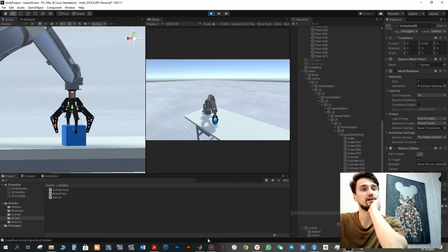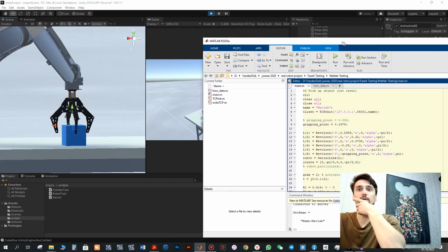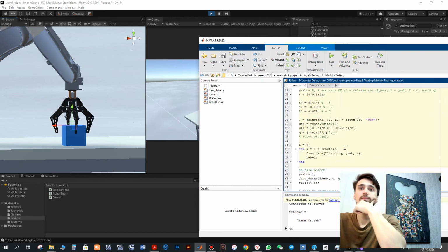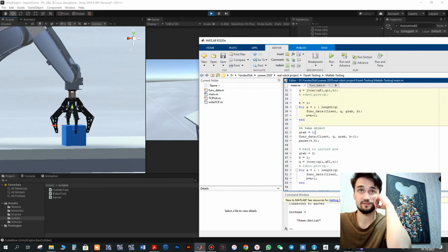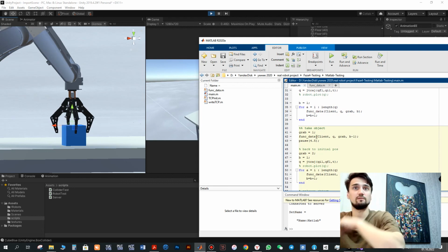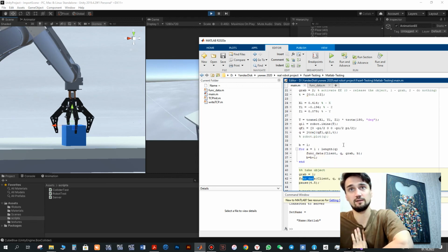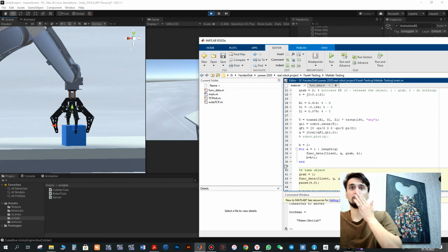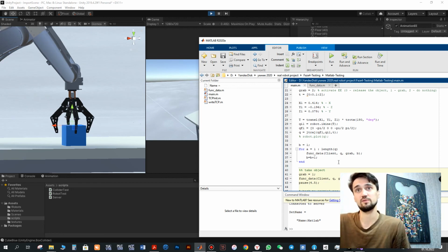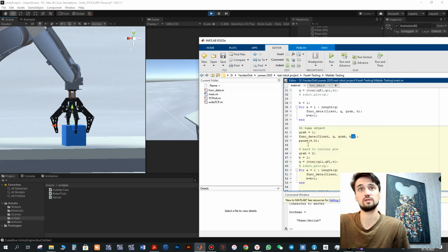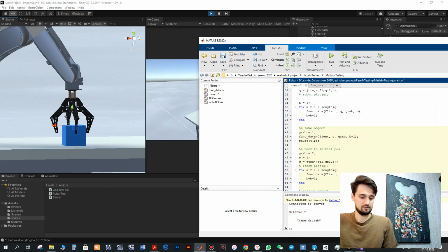During the next section we can grab our cube. So here we take object, we set the grab component equal to 1, which will grab our object, and again using function funcData. Here we use the previous robot position, so we finished position of our robot, but it was incremented in the previous step, so we need to use b-1 to use the last position of our robot. So let's run just this section number 2, so we take the object.